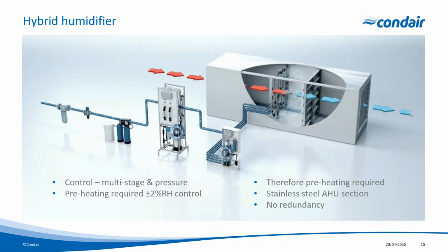Now in this instance, we're not using electricity to produce steam, but we still want the water to change its state from a liquid into a gas. And to do that, the water is going to suck heat energy out of the air, as it changes its state from a liquid into a gas. So the net result is that we need to preheat the air to give the air that energy required for that change of state from a liquid into a gas.